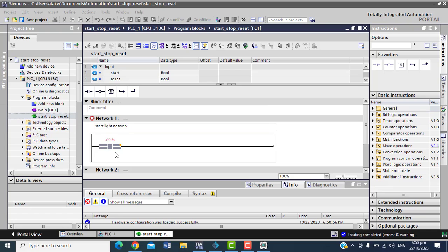So I call the normally open. Why do they use normally open here? Because you can switch to normally closed if you want. If you want to change anything, you see this small orange icon, where I click there. You can change them to normally closed or normally open. But I want to leave it as normally open, because you know it's a start button.